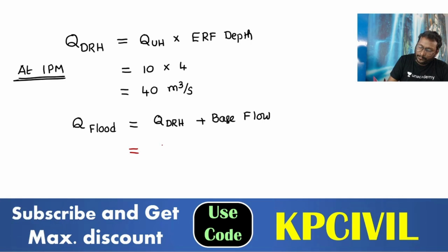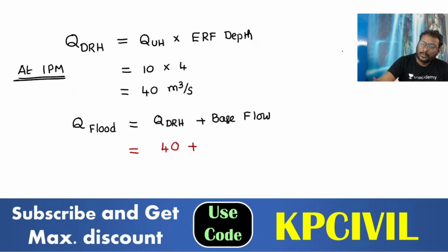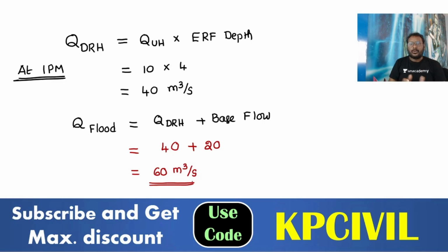How can we write it down? 40 plus, what is the base flow? Base flow is given, na? Base flow is 20 meter cube per second. So 60 meter cube per second. Q flood is equal to 60 meter cube per second.